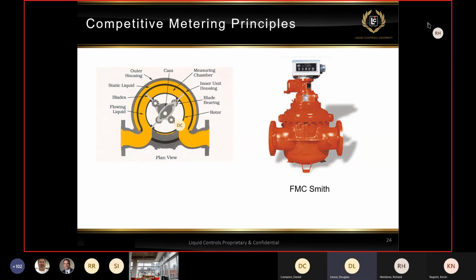So as the rotor is turned, the cam forces out against those bearings, and then the blades go against the inner meter chamber. That causes it to wear also. That's why they have multiple products that are used for blades. And in some cases, they're using bronze blades. So that's one that will wear, and over time, the accuracy of the meter begins to falter.